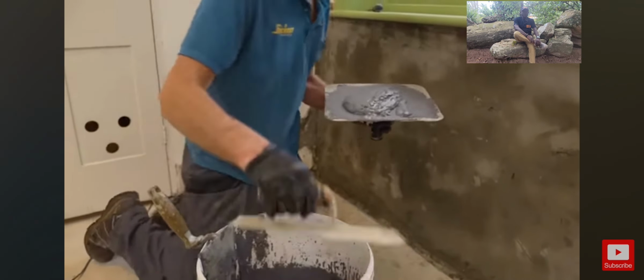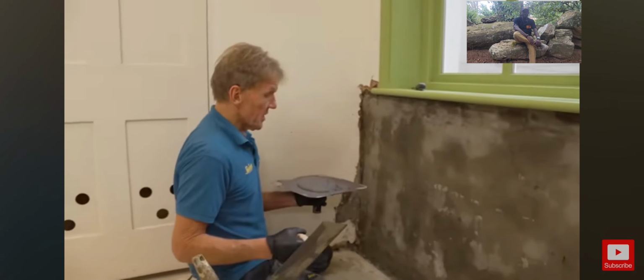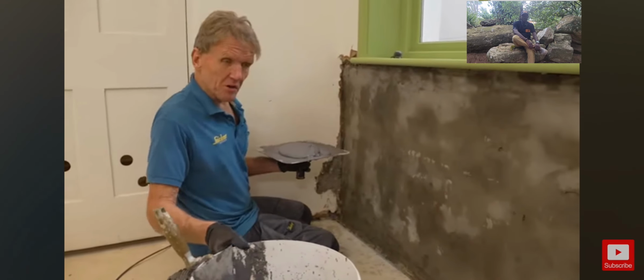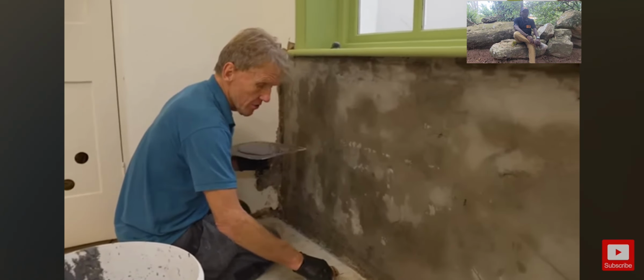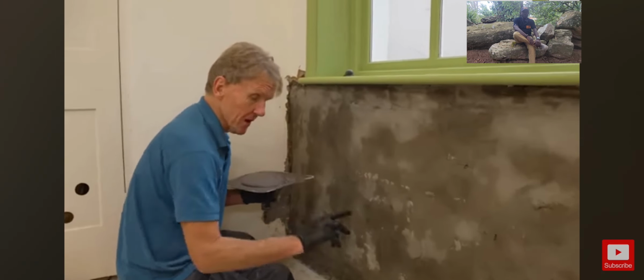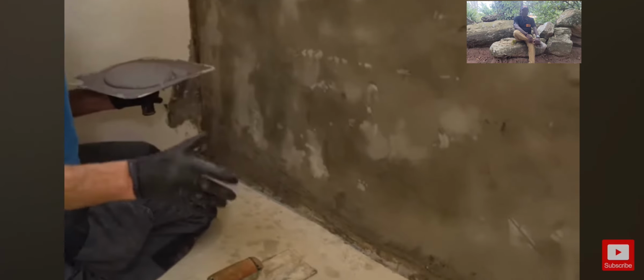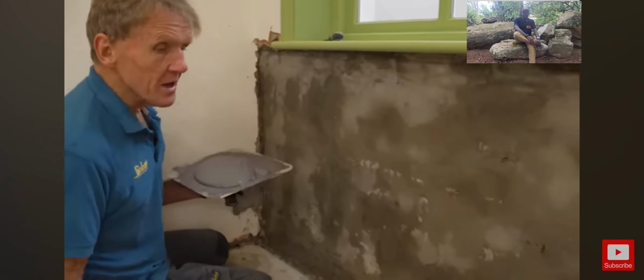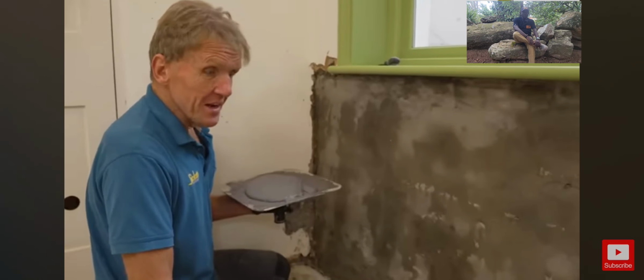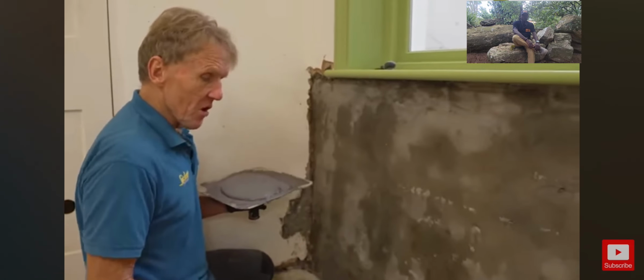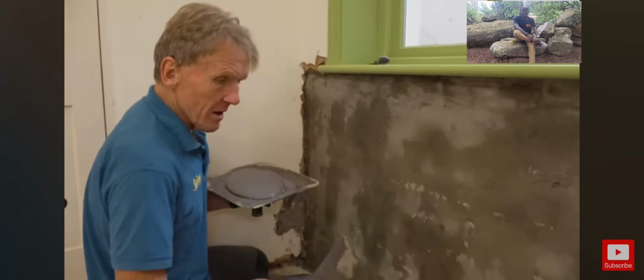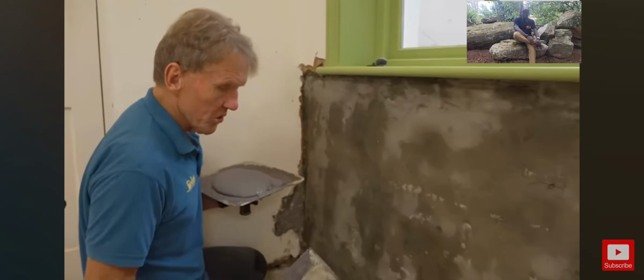Now normally I'd lay a board down on the floor to catch the drop-ins, but actually what I want to do in this case, I want to run this over the screed. We might put a fillet in some cases, but that would normally be before you've put the concrete in. So there's various ways of doing this. What I would say is if you need any guidance on this, get in touch with Safeguard, because they can give you a kind of a plan, if you like, on what you should do.